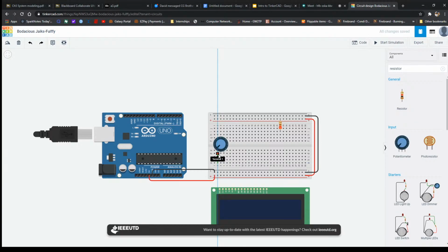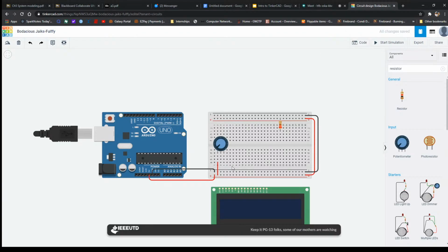But yeah, since these are all part of the same terminal strip, they all share the same value, same power essentially. So we're going to be connecting this directly to the power bus on the breadboard. And since this is 5 volts constant power, we're going to be setting this to red, just like these wires right here. And then the same thing for terminal 2, but terminal 2 will be for ground. So we're going to be connecting terminal 2, or this terminal strip, to ground, and we're going to set that to black as well, since it is grounded.